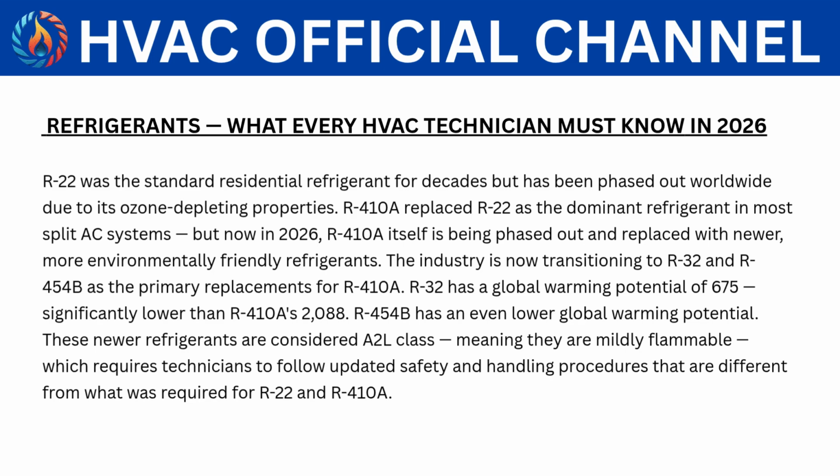R32 has a global warming potential of 675, significantly lower than R410A's 2088. R454B has an even lower global warming potential. These newer refrigerants are considered A2L class, meaning they are mildly flammable, which requires technicians to follow updated safety and handling procedures that are different from what was required for R22 and R410A.